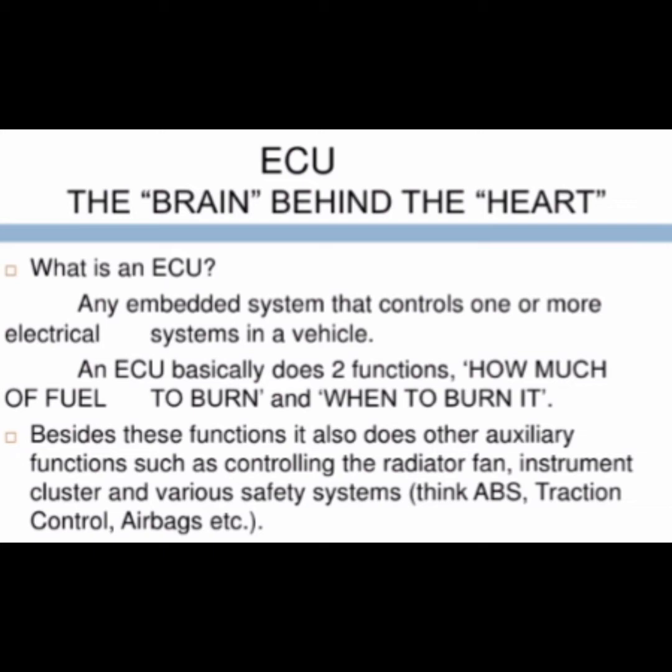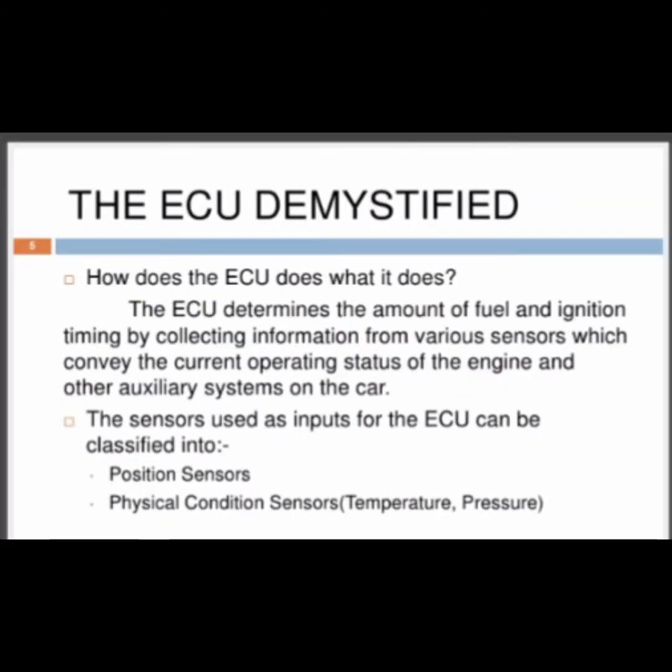The other function is auxiliary control of the radiator fan, the instrument system, ABS, and other controllers. The ECU does what it does by determining the amount of fuel and the ignition time, collecting information from various sensors which convey the current operating status of the engine.